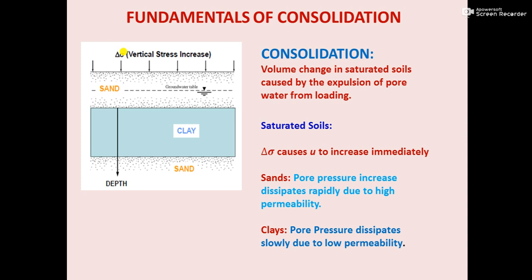So to go to the low energy state, what will it try to do? It will try to dissipate that pore water pressure. And how will it dissipate the pore water pressure? It can only dissipate if it goes away from the clay soil. And this going away from the clay soil, because of the low permeability of soil, is a very slow process. That is the main thing you should understand. So the consolidation process is a very slow and time dependent process. It will not happen in a single day.